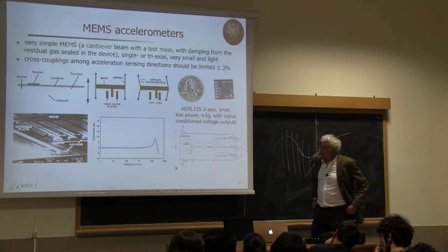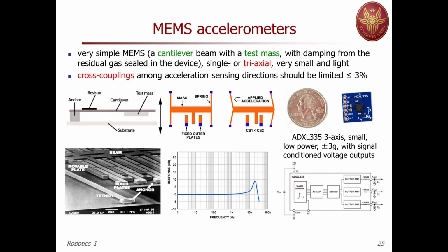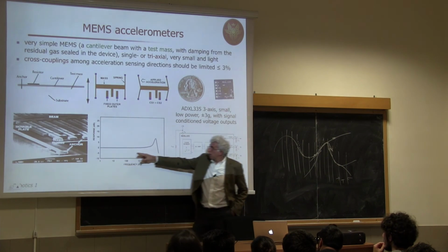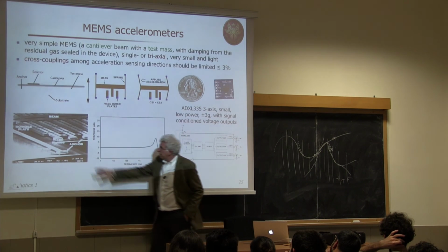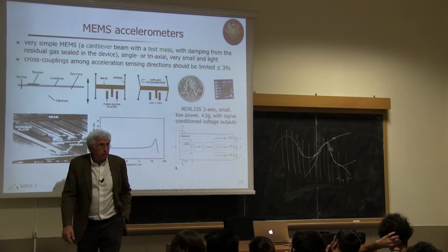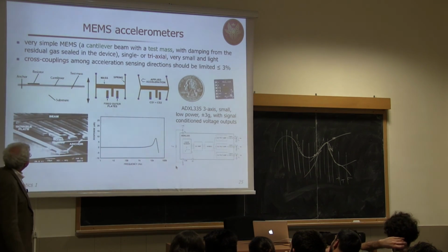And for a MEMS accelerometer, you have pretty much the same principle. These are capacitive, so this is a frequency response going, well, here from 1 hertz, but even beyond, you have still 0 decibel, so unit gain. Then you have some resonance, and then you have the same behavior as before, but you don't have this leakage at low frequencies.